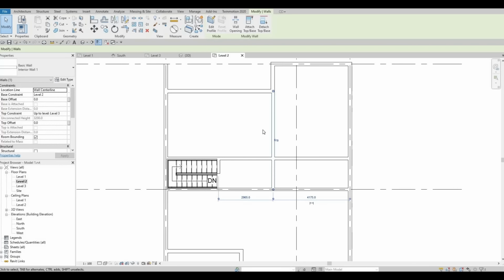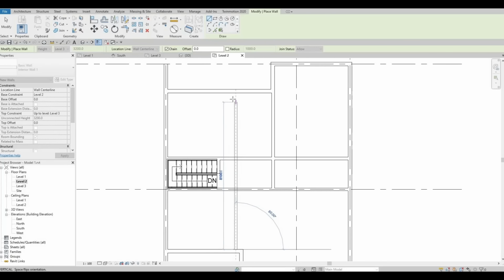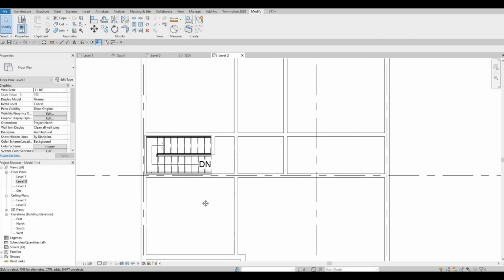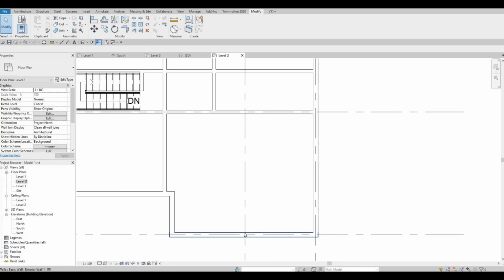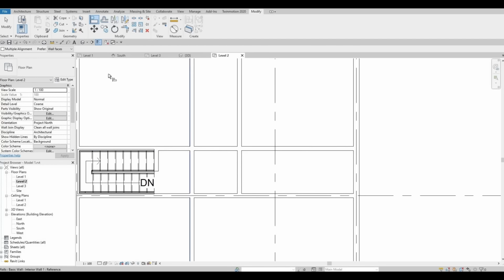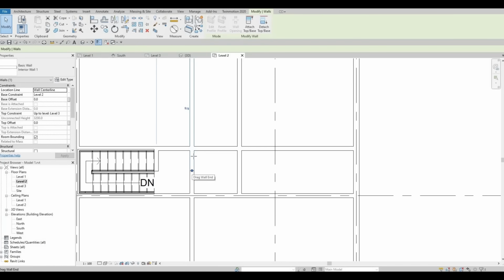Let's add in another wall. So this wall, so same wall, so CS again for interior wall. Let's add it all the way down there, but we're gonna align it again on this face. So AL, and then so this face to this face. So don't worry, we're just going to split element, so SL. So split this one and then just drag it upwards and then this one downwards.